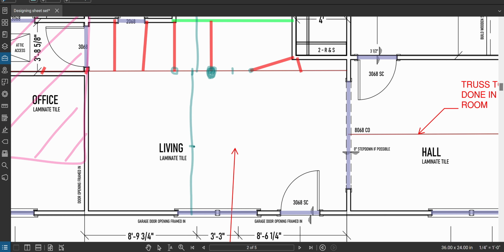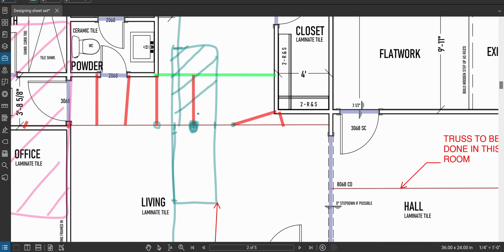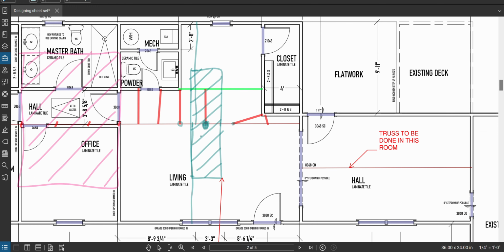Somewhere along this halfway, I'm responsible. Okay, so what am I going to do? I'm going to draw a rectangle from here over to here, up to here, to here. That is my tributary area that this brace is responsible for holding. That's where all the weight's going.